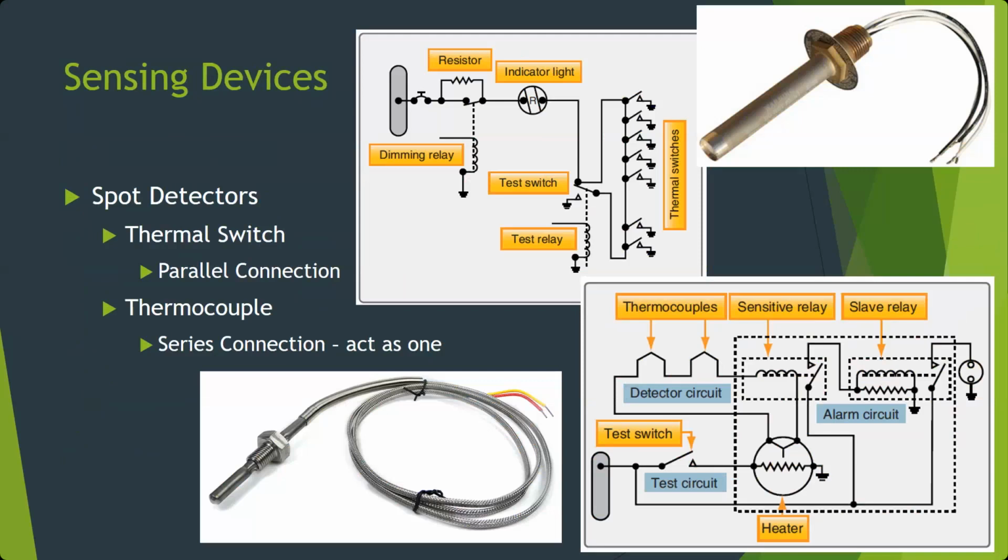A thermocouple, your other type, is still a bimetallic. Don't confuse it. Nothing moves in the thermocouple, remember. The most common are chromel-alumel style. Where you have those two dissimilar metals joined, as it heats up at that joint, you get a voltage difference between the two different metals. You get a potential, and so you can detect that voltage difference in order to send out a signal.